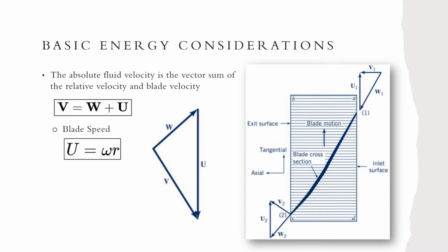The image displays a cross-section of the fan blade with velocity diagrams showing the absolute velocity, relative velocity, and blade velocity at the inlet and exit of the fan blade section. The key takeaway from this sketch is that the fan blade pushes the fluid, causing it to change direction. The absolute velocity vector is turned during its flow across the blade from section 1 to section 2.